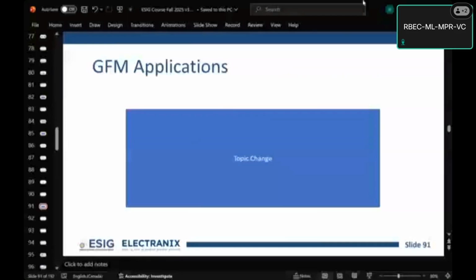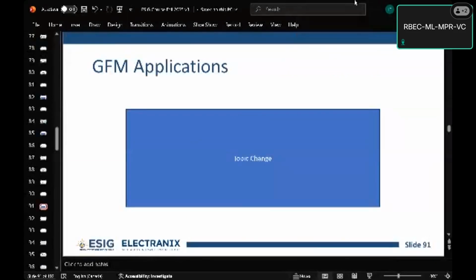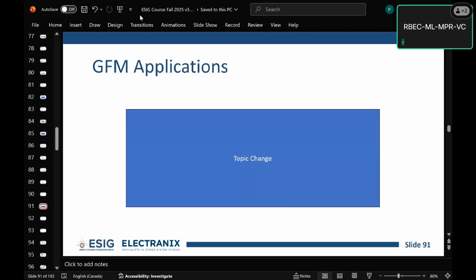So we need to just kind of apply those things back to phasor domain as well, because you can do a lot. There's a massive gap between the best phasor domain models and the worst phasor domain models, even amongst the major OEMs. So, which is really important to keep in mind, that phasor domain positive sequence modeling isn't going away. But the things that sound cool that we agreed to for EMT, you can still do in those tools. So it needs both.